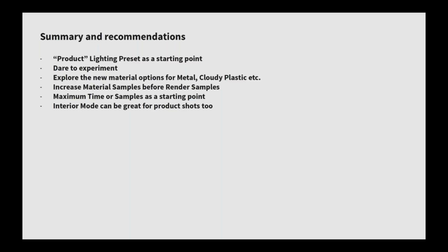Dare to experiment with cloudy plastic, experiment with the different parameters and perhaps try to match some physical examples of clips and plastic parts you may have lying around on your desk. As far as samples go, increase the material samples before the render samples, because that allows you to focus the samples on the materials that most need them. Maximum time or maximum samples is a good starting point. If you are running into situations where you have a lot of shadow areas, it can make sense to use custom control or interior mode.